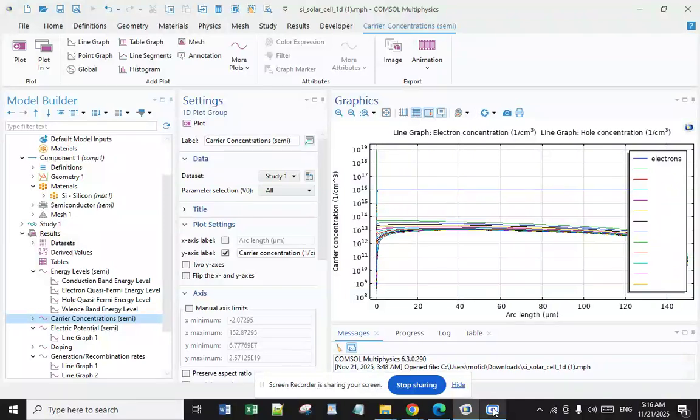And what about the back contact cells? The first step is placement. Both positive and negative contacts are on the back surface, and the pros or benefits: it maximizes the active area for light absorption on the front side, which increases efficiency. And the disadvantage is more complex and expensive manufacturing.